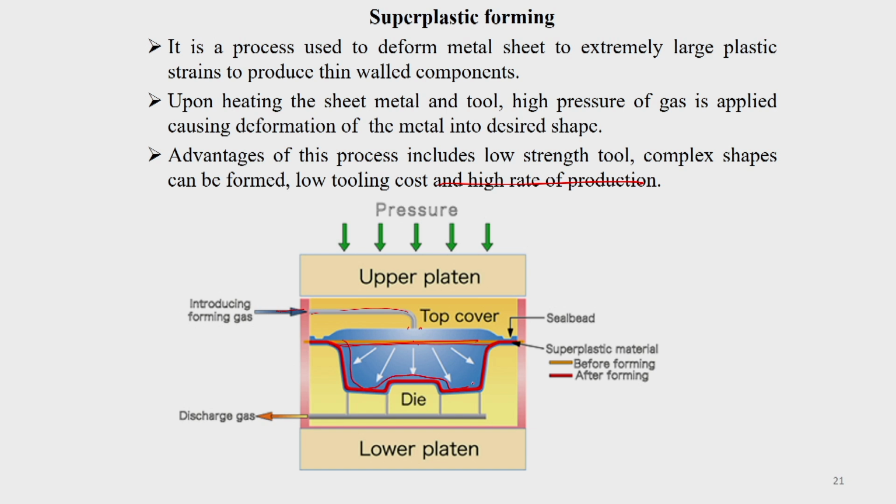Because necking is not taking place, fracture will not take place. The only thing is that this has to be carried out under those particular conditions. The biggest advantage is that for a material such as titanium, aluminum, vanadium, which is an extensively used superplastic material, used in a big way for space and defense applications, the sheet is kept in place and you apply the pressure at a very slow rate.